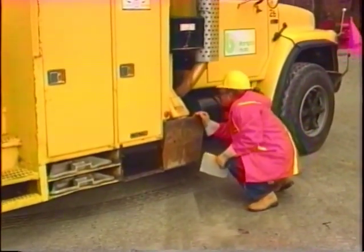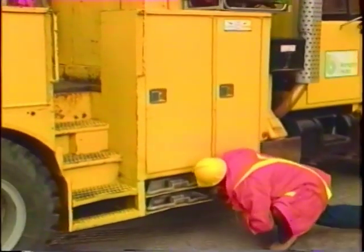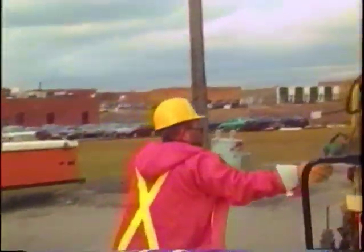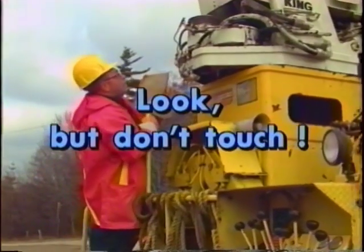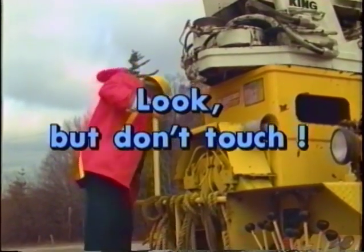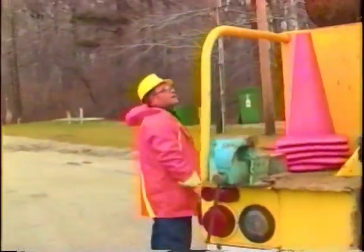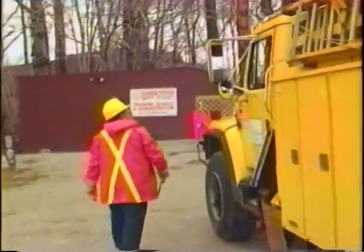After finishing at the reservoir, carry out the rest of your circle check. As you walk around the vehicle, look for fluid leaks, damaged hoses, loose fittings, and so on. This is a visual check only. Do not feel for leaks. Hydraulic fluid pressures can be as high as 3,000 psi. If you put your hand in front of a high-pressure fluid leak, you can be seriously injured. In the next section, we'll go over vehicle setup and holding valve checks.